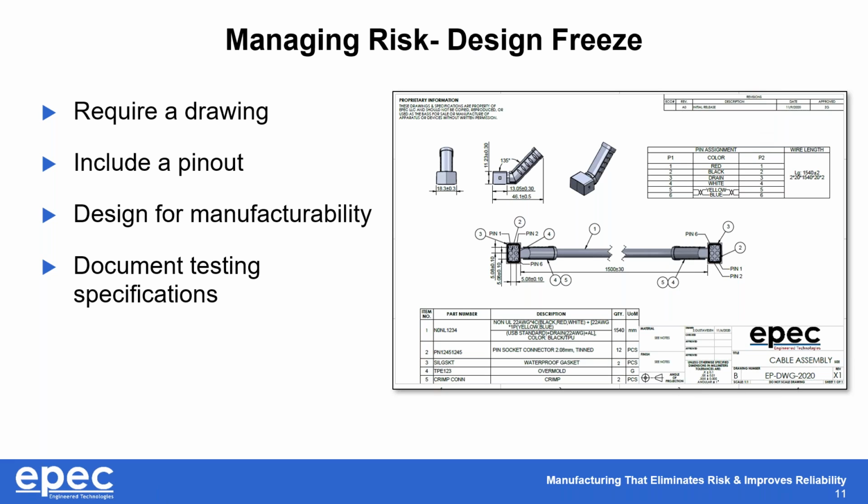Lastly, most cables come with the assumption that continuity is tested. This is standard. Obviously, the cable needs to electrically pass current to be functional. Continuity is typical. But if your project requires testing above and beyond this, like an IP67 waterproof test or some kind of pull or flex test, these are important test specifications that must be clear early on to your supplier. Otherwise, you can run into risk either during development or after shipment, finding out that your widget doesn't actually meet the design objectives.